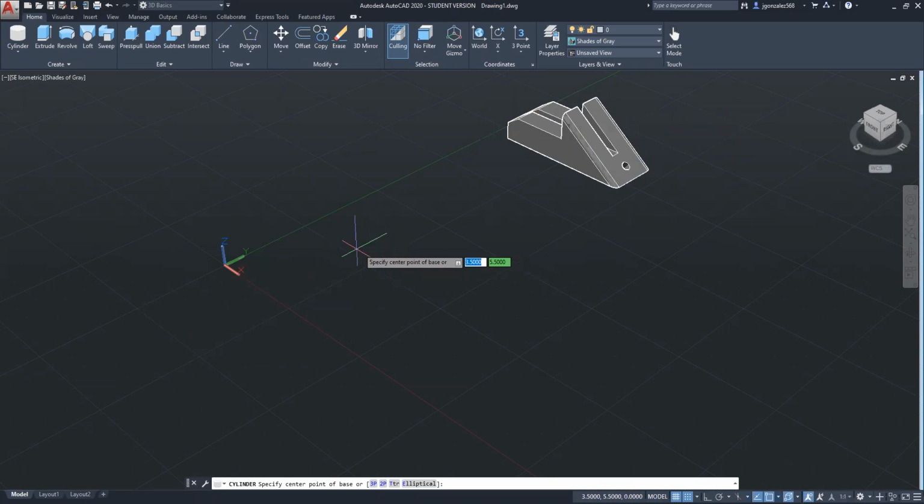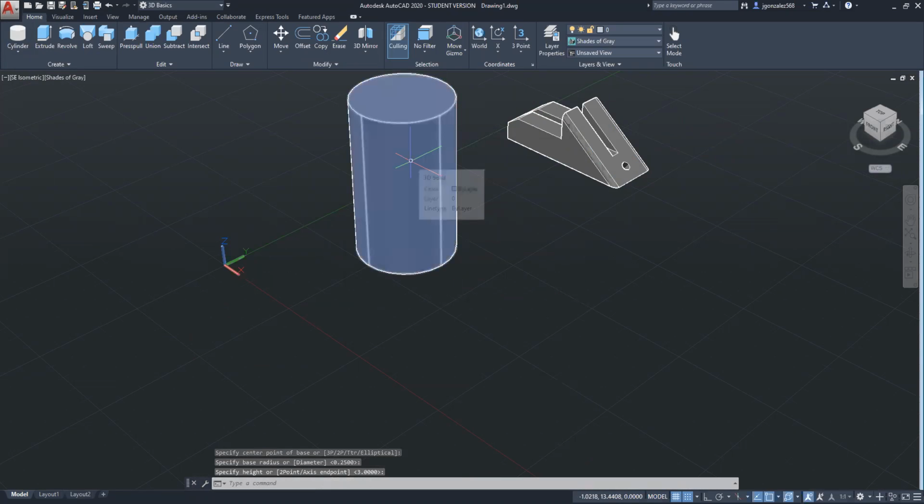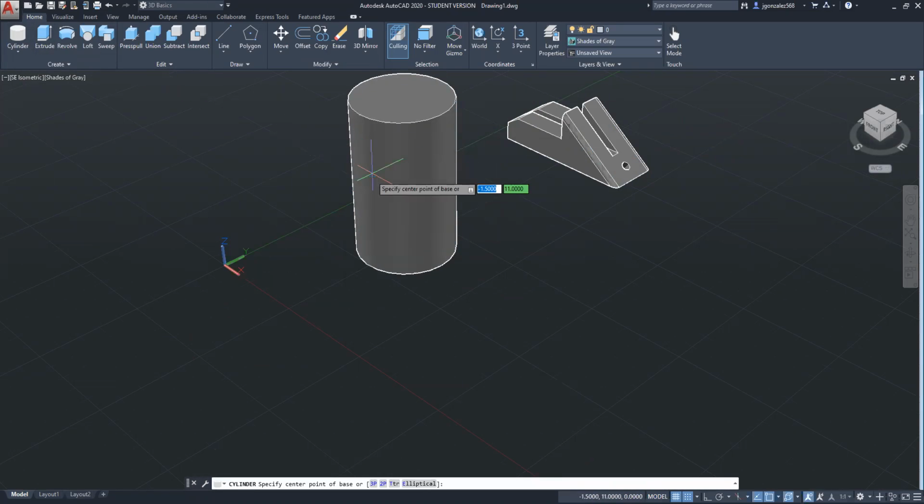Anyway, so I want you to make a cylinder. Choose the functions here and choose cylinder. It doesn't matter the radius, just make whatever, 2.5 is fine. Make it about 8-ish. Let's draw a little cylinder here. Then I want you to draw a cylinder inside of it.